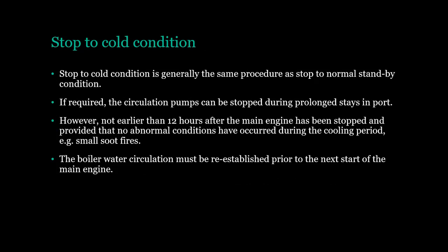Stop to cold condition. Stop to cold condition is generally the same procedure as stop to normal standby condition. If required, the circulation pumps can be stopped during prolonged stays in port. However, not earlier than 12 hours after the main engine has been stopped and provided that no abnormal conditions have occurred during the cooling period, e.g. small soot fires. The boiler water circulation must be re-established prior to the next start of the main engine.